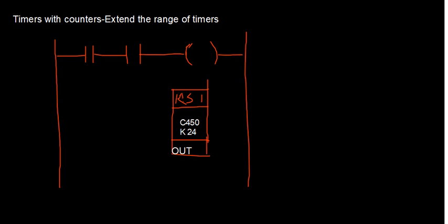Okay, reset. I am using a counter with the nomenclature C450 and K equal to 24 and out. Now you can see I am using one more rung here, that is to reset your counter.